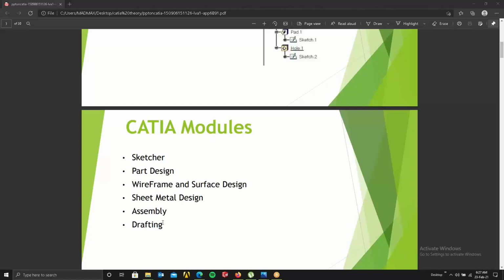One of the main problems that you're going to face is when you're transferring the file to somebody, like if you're sending it to the manufacturing person. The moment you save it and just open and rebuild, if the constraint is not proper, the sketch is completely changed. The sketch will completely change the moment you share the file and somebody else opens it. That's one of the greatest problems that you'll face.